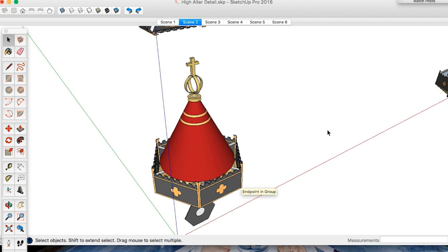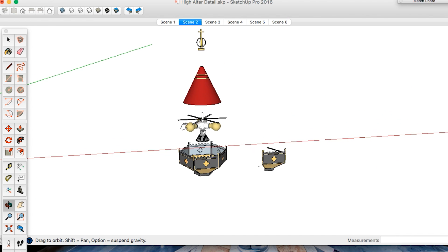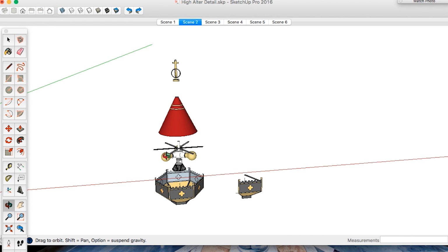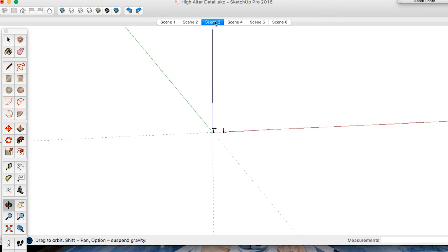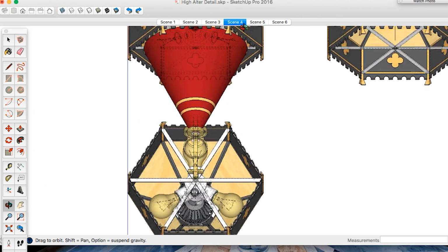So take that, have that as the 3D model there, and then just do sort of an exploded view. Anybody do exploded views in SketchUp? So the biggest trick that I've found is to always move the objects the same distance. It's all visual, but each one of these is moved up 2 feet or a foot, whatever graphically can be set. But then also, you'll see those viewports or scenes are created here to better help.